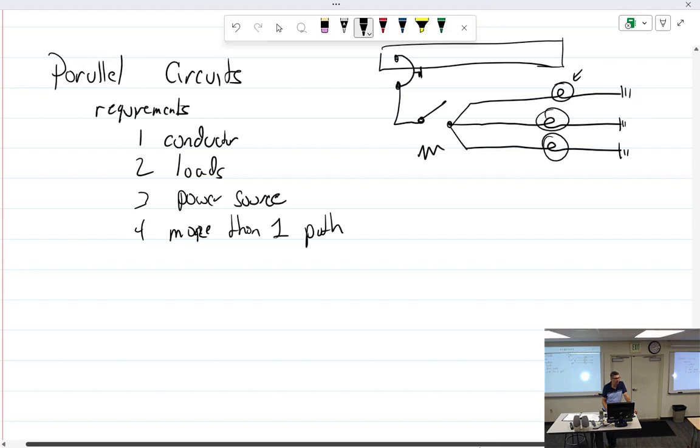So let's say I take the switch out, and what do I use? Use an ohm meter. Well, I could take the switch out because we can't check resistance with a load, so we can turn off the master switch. It'll be fine. Be aware, though, when the master switch is off, it does not kill all power to the back of the panel. I have an electric clock in my airplane that takes power from the battery through a little tiny fuse all the way up and through.